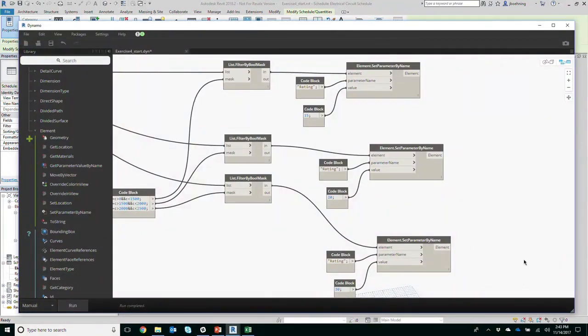I'll leave this up here if you're having trouble seeing it. So, does that make sense, kind of what we did? We selected circuits, we got a parameter value, and then we filtered them out based on a certain condition. In this case, we did two sets of that. We filtered it out by the voltage, so we only got 120 volt circuits, and then we created some ranges as far as what value we wanted to use to set the parameter. Everybody good? Make sense? If you're having trouble, raise your hand, please.